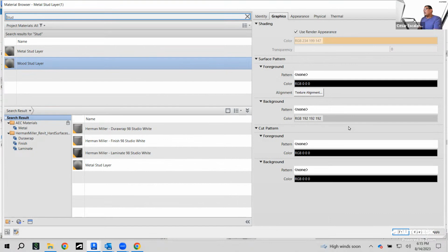It's up to you, and you may also choose to display. The thing is that when we're creating these layers of stud, it's not like Revit is going to build the stud profile at a specific distance. All we're saying is that this layer configuration is going to hold studs, and it's going to look like this, but it's just a schematic representation. It's not going to place the stud for you. It's just holding the layer thickness that is needed to make the partition geometrically correct.